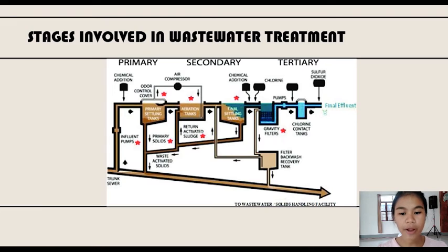So when we say primary, dito natin tinatanggal yung mga plastics, the rugs, the bottles, yung mga solid niya na nakahalo dun sa tubig. And then, yung arrow, tignan natin, nagmo-move siya papunta sa aeration tanks. It enters now the secondary treatment. Dito sa aeration tank, dito mangyayari yung 90% na natitreat na ang tubig because yung grease, yung mga other contaminations are removed through that aeration tanks.